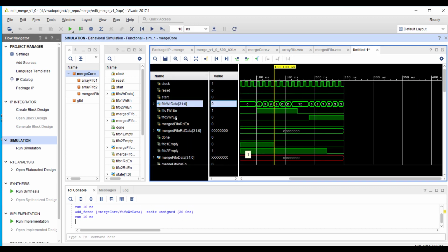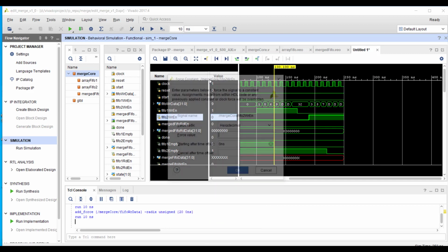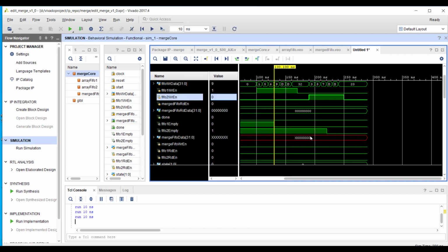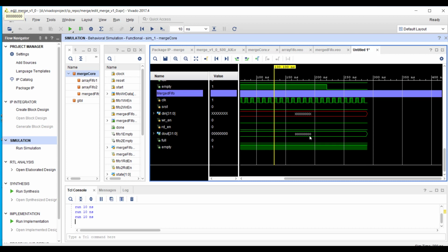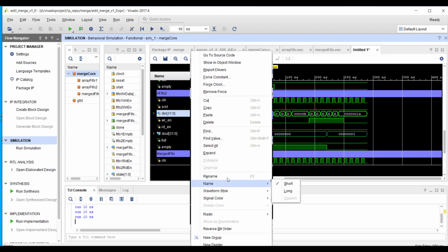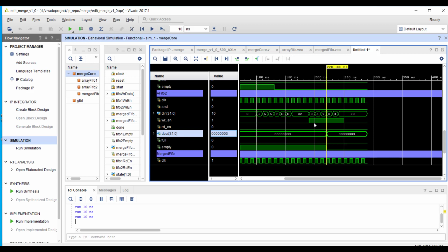Okay, so in a real case, the processor will be writing these values through the X interface. Same data should be going to the second FIFO. So you'll see the first data is also coming here, but the write enable signal is low because we connected the same data signal to both FIFOs directly. And the same data, fine, and its output already became 3.